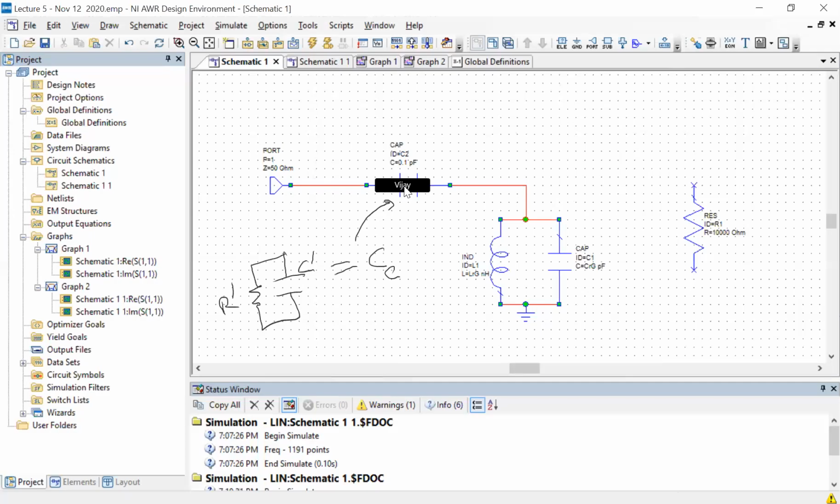This capacitor just shows up in parallel with the original resonator, which is why the capacitance adds, as I mentioned a little while back. Then R prime will have a slightly more involved expression. It will depend on the original R, and it will depend on the coupling capacitor.